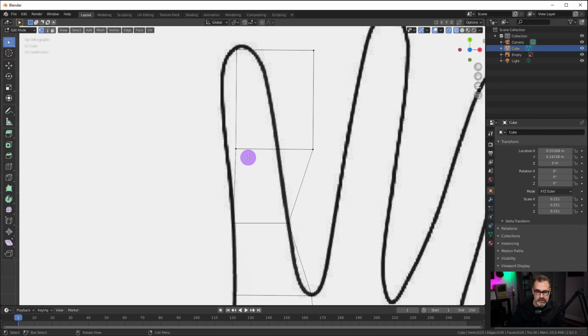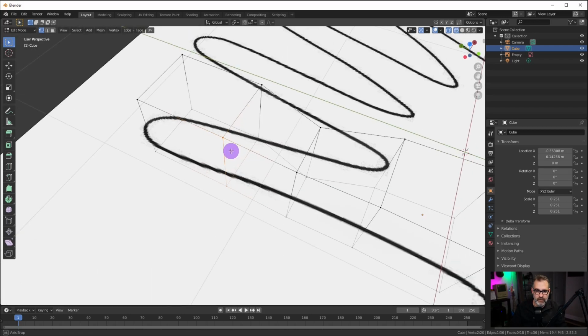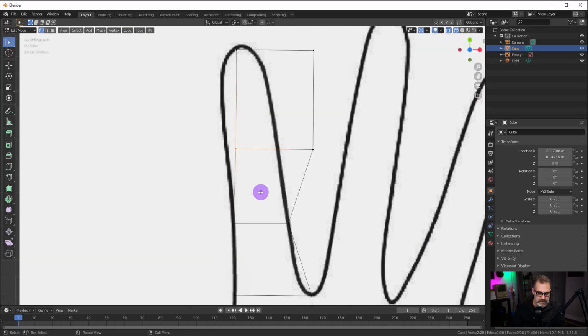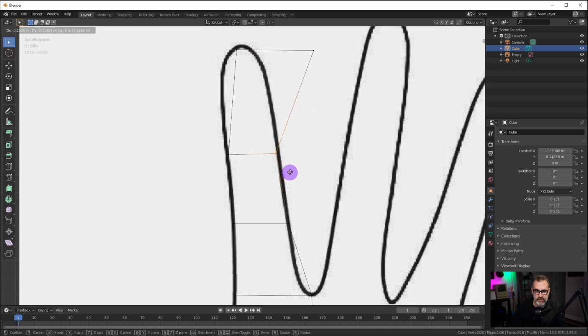The other thing you can do is use the C key. Okay, it'll do a circular select. If I rotate around, I can see that both vertices are selected, the front and the back. I prefer to do box select. I don't know why, that's just my preference. And the G key for grab, and double press A, box select, G key for grab, double press A, and once again, wash, rinse, and repeat. So it's a lot of pressing the B key, the G key, and the A key to deselect.